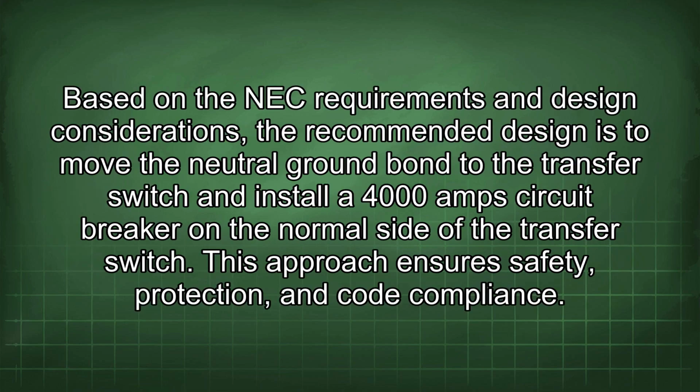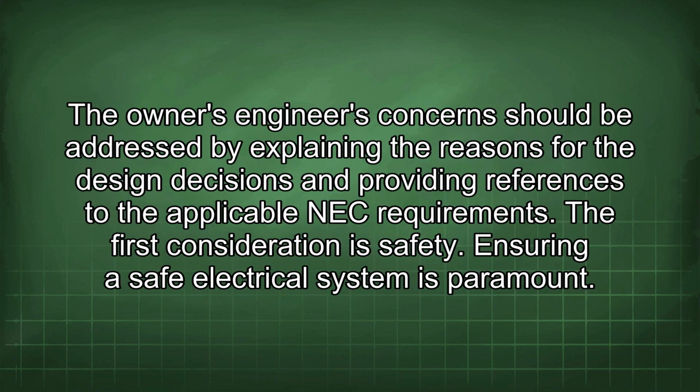Based on the NEC requirements and design considerations, the recommended design is to move the neutral ground bond to the transfer switch and install a 4000 amp circuit breaker on the normal side of the transfer switch. This approach ensures safety, protection, and code compliance. The owner's engineer's concerns should be addressed by explaining the reasons for the design decisions and providing references to the applicable NEC requirements. The first consideration is safety.